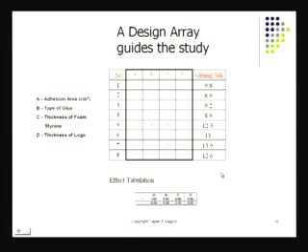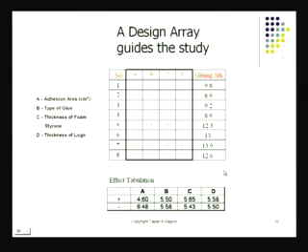I take this data and I do some calculation. Those calculations basically show me the effect of changing A from low setting to high setting, and look at the impact. Gluing strength changes. I do the same thing for B, C, and D. These calculations have been done in a special way by starting with these input conditions and by looking at the structure of the matrix. Once I've done that, I am able to calculate these factor effects. Now what this is showing is, when I change from plus to minus, these are the 2 settings for A, gluing strength changes.